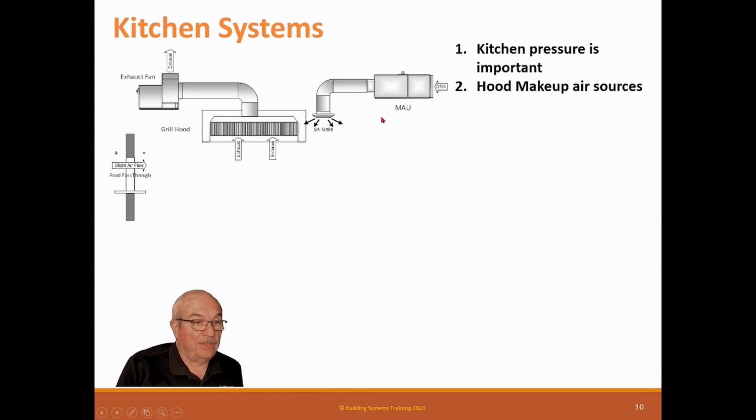If not, they're going to get hot and they're going to turn them off. That's the problem. You know, if you're in a humid area and this is an evap cool type thing, it won't do any good. So if you got a humid space, this needs to be an air conditioner. Now the problem is, again, it's bringing in 100% outside air to make this up. So there are different makeup sources.